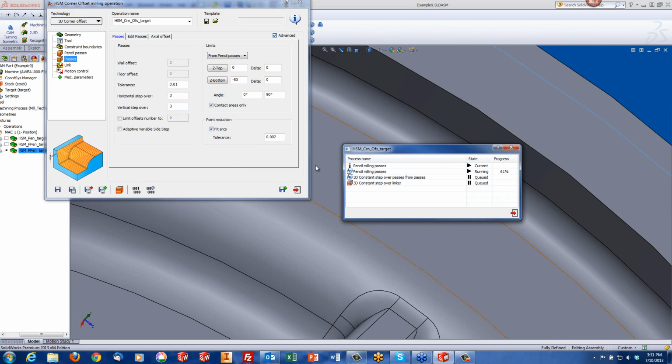Well, remember, I'm not using a bitangency angle this time. So my borders will not necessarily be on every single edge. Some edges it will pick up, and other edges it won't pick up because of the bitangency and because of the over thickness between the tool and the area. So let's see exactly what kind of toolpath we will get without doing the over thickness, since it does have to work on the entire area that I marked off. One more moment.